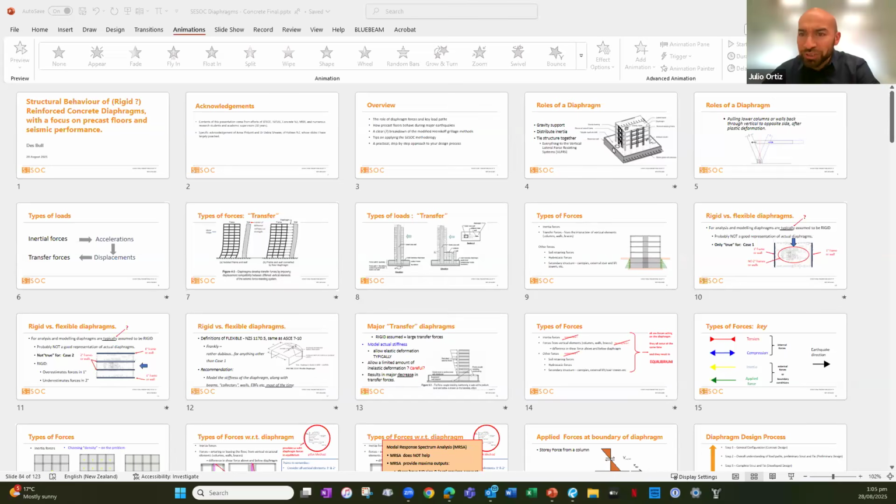From Tom Lindsay: most precast floor systems with a topping generally end up with cracking over the supports as the topping tries to make adjacent spans continuous. Do we need to account for these tensile forces in addition to the diaphragm inertia forces when analyzing a diaphragm? Sorry, do me a favor and say that one again.